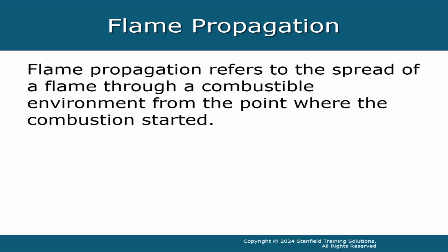Flame propagation refers to the spread of a flame through a combustible environment from the point where the combustion is started. Both the ASTM standard E681 and the ASHRAE Standard 34 use the term flame propagation. We have a tendency to read past terms that we are not familiar with and mentally substitute more familiar terms in their place. No flame propagation does not mean no flame. The word propagation essentially means spread. The term flame propagation means spreading of flames.